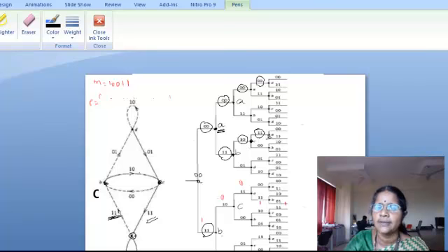And then from this point, since this is state A, if you go up, that means if you encounter an input of 0, then you will come to the same state A with an output of 0 0. Right. And now from state A, if you encounter an input of 1, then you come to state B with an output of 1 1. So whatever we saw in the lower part will come here.